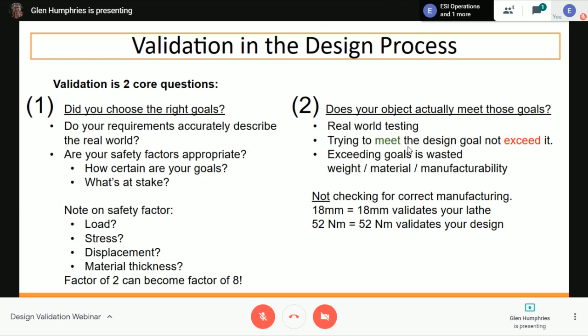It's something that came up last year. We had a team that had a certain load for their drive shafts, a certain amount of torque. They then, I think, chose a safety factor of 2. That's fair enough, as long as they can explain it. And then they apply that safety factor of 2 to the diameter of their drive shaft. And those of you who've studied torsional stress within a cylinder would know that that causes a much bigger increase in the strength of the drive shaft.